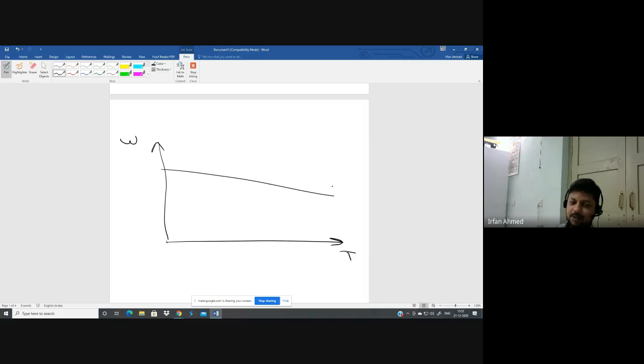How much speed your motor can handle depends on the mechanical considerations. So in DC motors, it is normal that you can have maximum speed up to 2 to 2.5 times the rated speed. How much? You can go up to 2 to 2.5 times the rated speed. If you want more than that, then by increasing the mechanical components, you can have greater speeds also. Okay, is that clear?